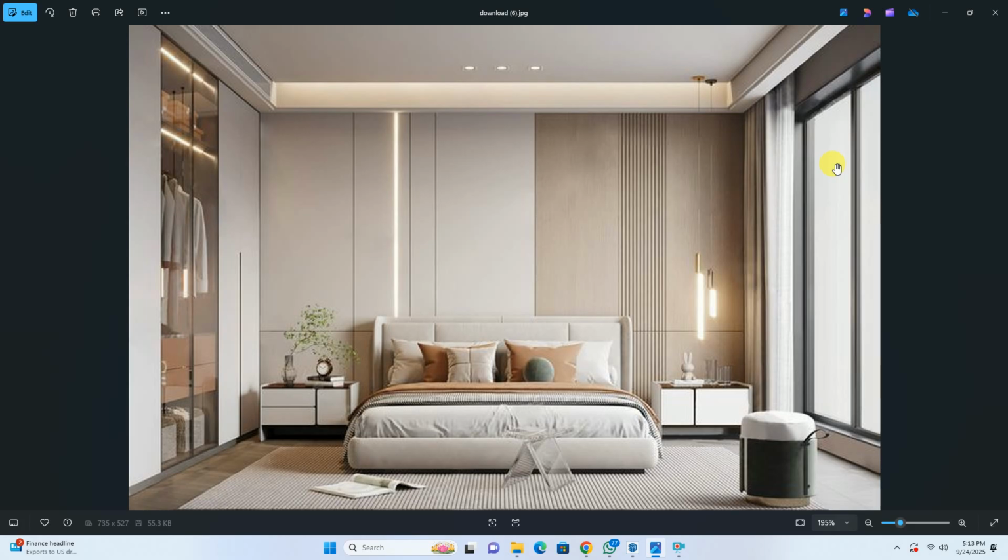UPVC, because the standard length of UPVC that is available to us is 8 feet to 9 feet. Second thing is UPVC is less strong as compared to aluminum section. If we want a sleek section, a luxury or grand look, then we will use aluminum sections. The costing of aluminum sections may vary from 1200 to 3000 per square foot. The costing of UPVC sections may vary from 500 to 1200 per square foot.